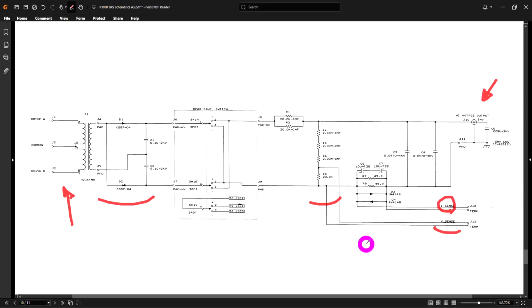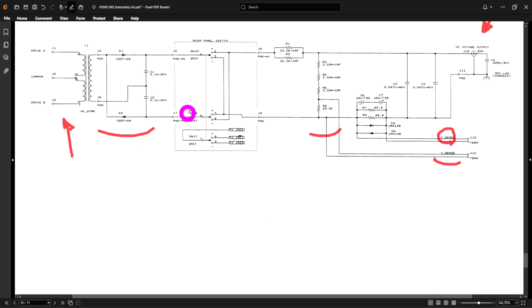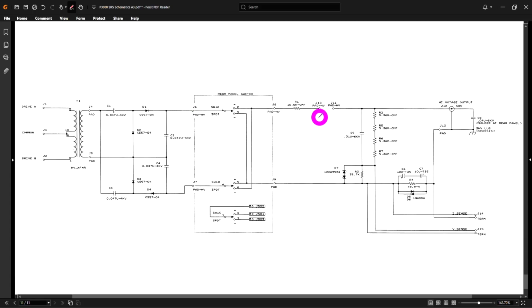Now if you want to reach 5000 volts, you don't need a doubler. Now you need to multiply by 4, you need a voltage quadrupler, and that's exactly what they do in this final version of this. Now if you notice, everything else is now rated to 6000 volts. This thing goes to 5000 volts, but here you go. Now you have twice as many diodes and twice as many capacitors. You quadruple the voltage.